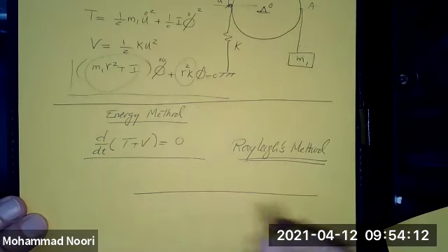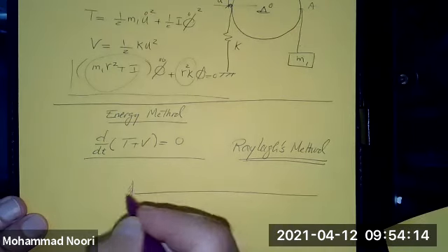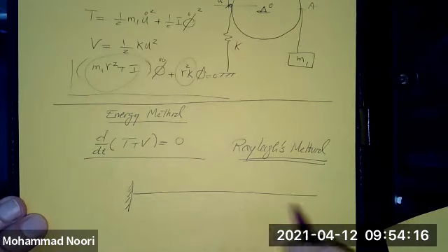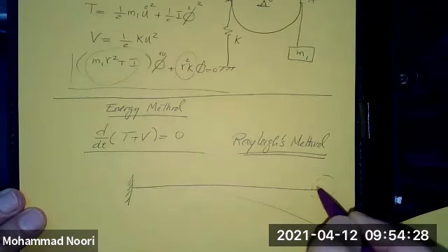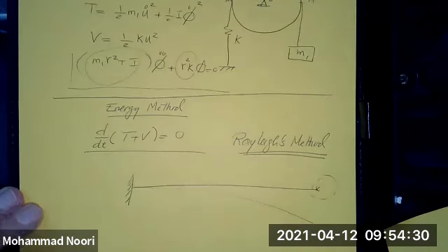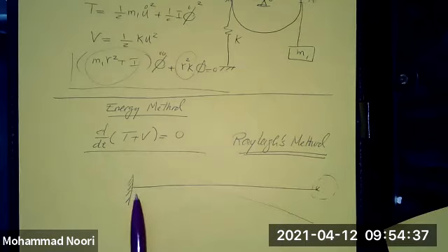We said that if you have a beam that consists of an infinite number of degrees of freedom, if you identify 1 degree of freedom, which is in this case the tip of the beam, which is our main interest, the maximum deformation, you can always relate the displacement of every single point along this beam to this degree of freedom.